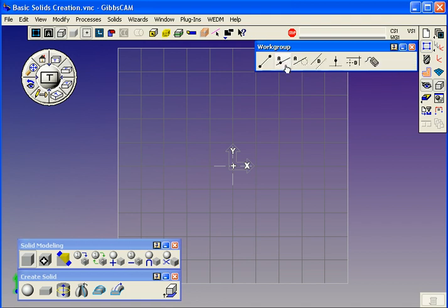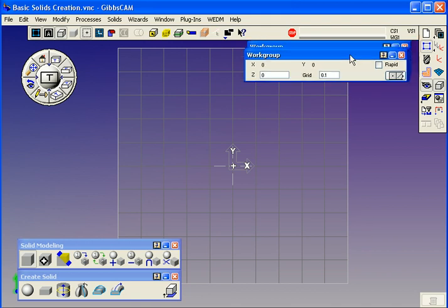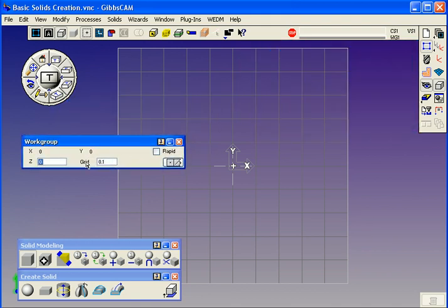What I want to do is select the line tool here and pick on the mouse line, and notice what happens when I bring up the mouse line palette. We get this sub palette here where I can set a grid snap. So what that basically makes me do, or forces me to move in 0.1 increments. It won't let me snap to an increment in between a 0.1 move, or you can make that whatever size you'd like. And as long as my cursor is inside the stock boundary, notice that here the display in X and Y shows me where the cursor is. I'm not going to pay a lot of attention. I'm just going to freeform a shape here, something that we can do some experimentation with in the revolve. Try and end it pretty much where I stopped it.